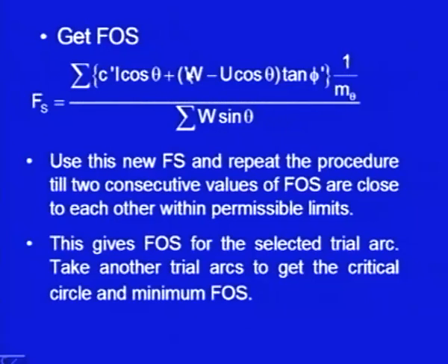So, you started with one value of F s and you use that value for all the slices, and then we get a new value of F s. Again use this new factor of safety, and repeat the entire procedure. Keep on repeating it. Every time you will be getting a new value, put it in the expression again, put it in the procedure again, and get consecutive values of factor of safety.